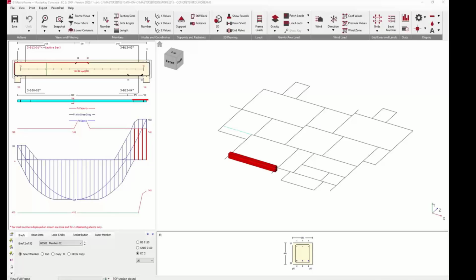Does the pile cap designer take into account the 75mm tolerance? Well, everything is assumed to be constructed correctly from a design point of view, but certainly, yes, there is a 75 or more allowance on the pile caps for the edges, the projections, and that allows you to have that misalignment. The misalignment in the piles themselves, that's part of your load factors.